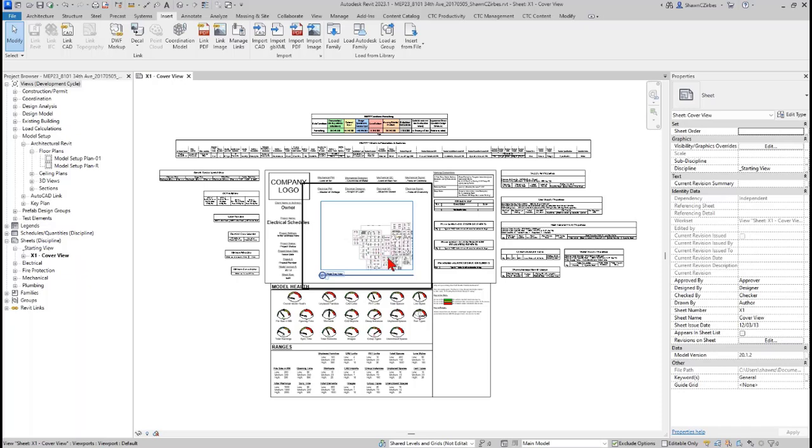So with this architectural model, their base point is set however the architect's base point is set. And one of the things that I always do is I use whatever the architects have done. If they've got their base point at 100 and they've moved it up, I move mine up. If they have it set at 0, but they named it to be 100, it's whatever. Whatever they do, I follow. I never, ever modify the architect's model or position in my project once I've linked it, because when they cross-link my project, I want it to just link in origin to origin. So I link it, there's origin to origin, and I leave it in place.